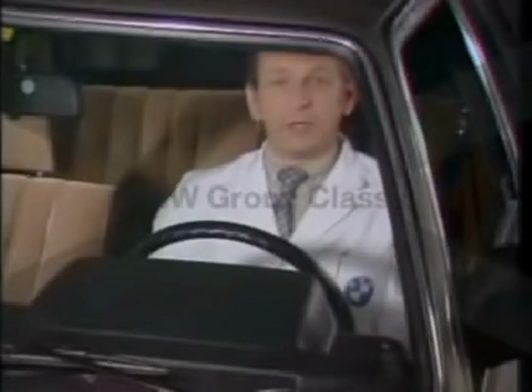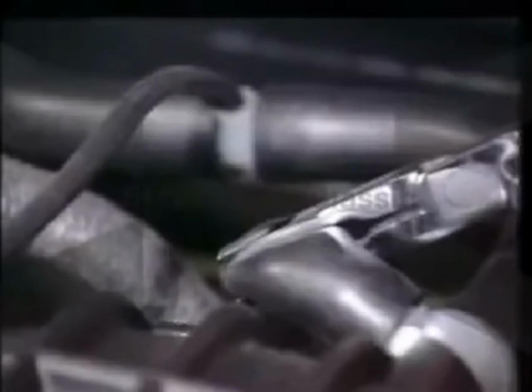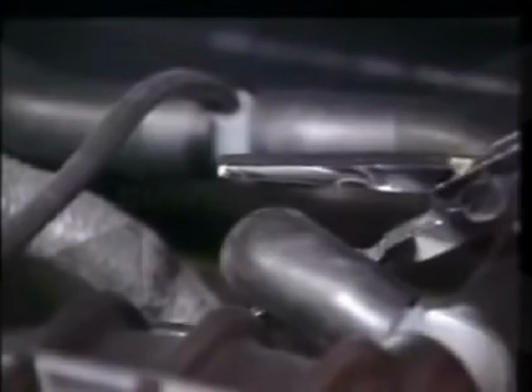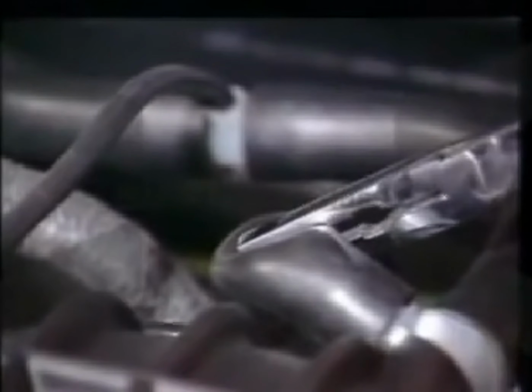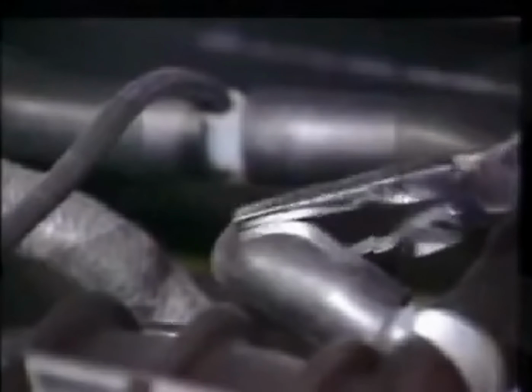After remounting the unit, the pipes are reconnected and the engine started. When the engine is cold, then if the air supply is interrupted by clamping the hose off, the engine revolutions must drop. Should the engine be warm, then there should hardly be a noticeable difference when the hose is clamped off. If this is not the case,